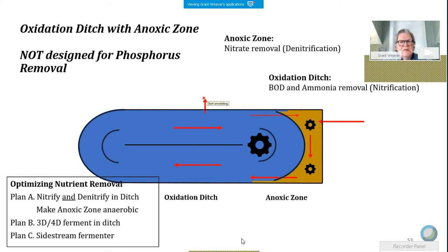If that happens during warm weather, the phosphorus that gets brought into the mixed liquor doesn't glom on that well, and it will release the phosphorus again pretty easily in warm water. So you have to go with an absolute minimum sludge blanket and a high rise rate, and try to keep that sludge blanket to an absolute minimum. So that's one scenario that happens.